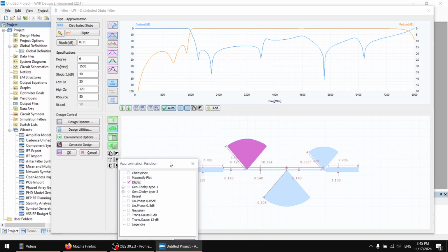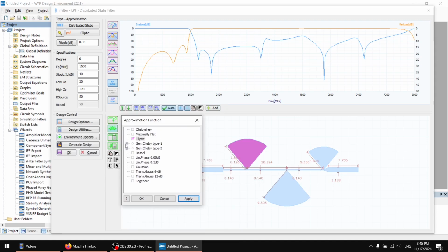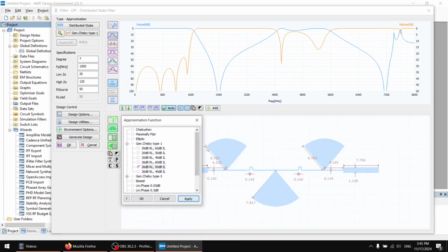If you are designing a real system as an engineer, you have to of course choose what suits best your application. Maybe you want to eliminate the harmonic of 1.2 gigahertz. Then this filter might be very good for that, right? If you care about the good return loss, so your reflections, this is quite a good solution, right? But some filters might be not so great.